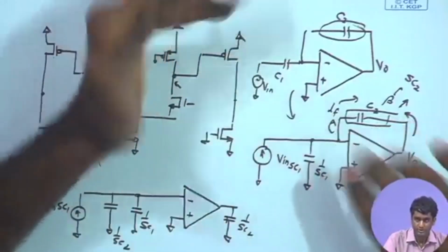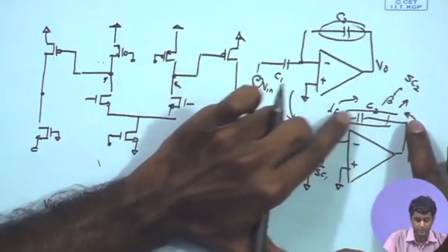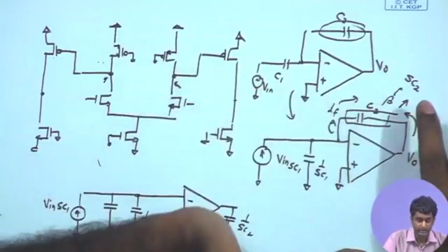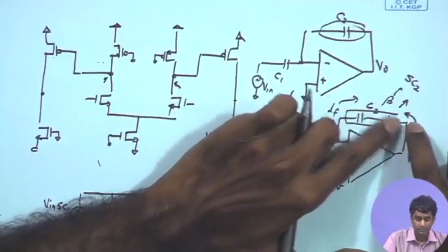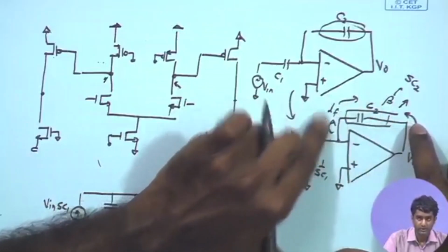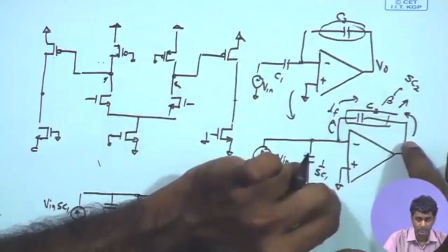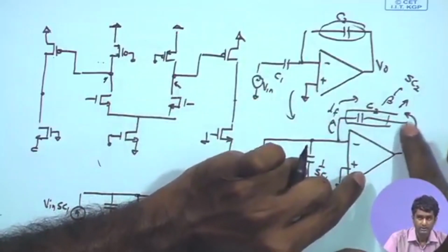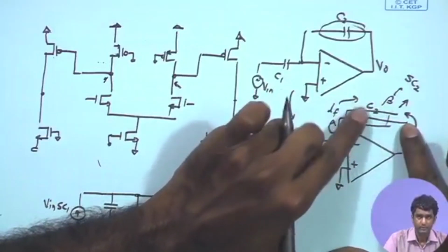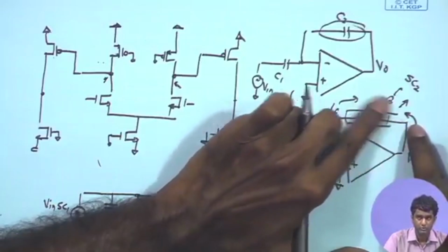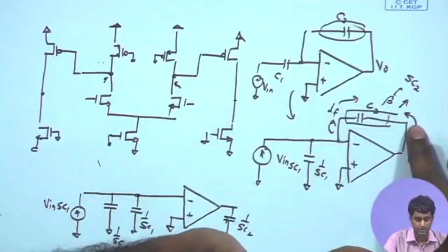Therefore, for assessing the overall voltage to voltage conversion factor, we would open circuit the output port of the voltage to voltage converter, and likewise while assessing the conversion factor for a voltage to current converter like this feedback factor, we would short circuit the output node, so that the feedback network is not loaded by the amplifier. So, we are trying to characterize this feedback network: given a voltage signal over here, what is the corresponding current provided by this feedback network, for the shunt configuration.